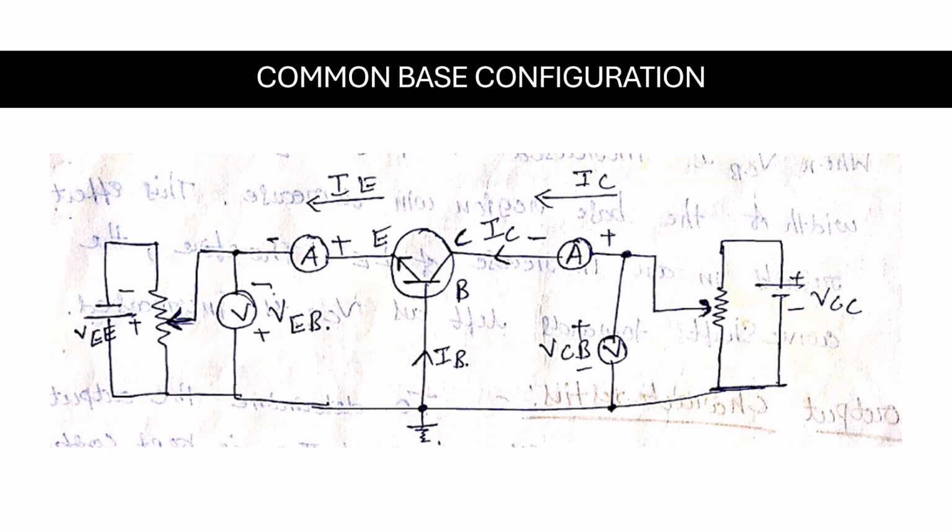The voltage at which the diode starts conduction, that means the current starts rising exponentially, is called the cut-in voltage. We discussed everything in the operation of the PN junction diode. Here the input junction acts as a PN junction diode in forward bias only. So the graph drawn between VEB and IE is nothing but the diode current, exponentially increasing.